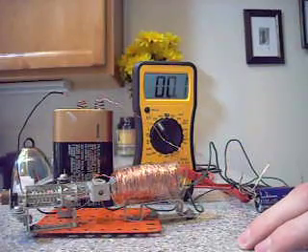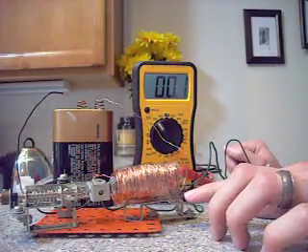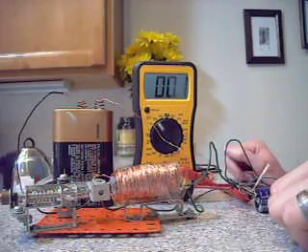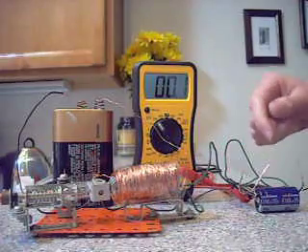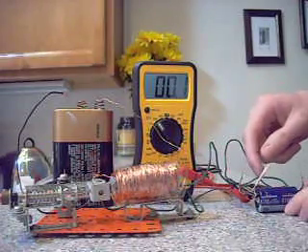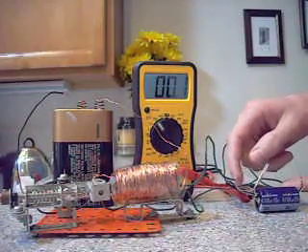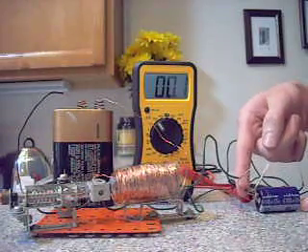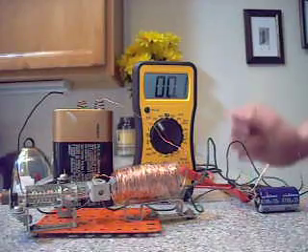And one curious thing about the way I set this up is the primary winding of the transformer actually doubles as the solenoid actuator for the buzzer. So it's kind of a dual function there. It eliminates a component by arranging it that way. Over to the right, you'll see a large capacitor, 4700 microfarad, maximum 35 volts. And here, I don't know if you can see, it's a little bit smaller, the rectifier diode.